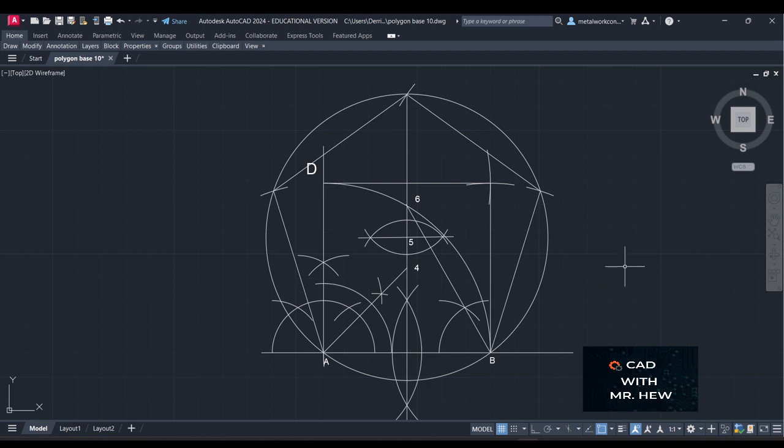Now, as I indicated earlier, the arc marked from 6, which is right here, this distance. If you take this distance from 5 to 6, take that measurement. If you're using a compass, you would put the compass point at 5, open it to 6, and then from 6 you would mark an arc to give you 7. From 7 you'll mark another arc the same radius to give you 8. From 8 you'd mark another arc the same radius to give us 9. From 9 you'll mark another arc to give us 10. Because from 5 to 6, that would represent the centers of the circle, which would give you the polygon that you want to draw. All right. So if you want a 6-sided figure, we're going to repeat the same process.